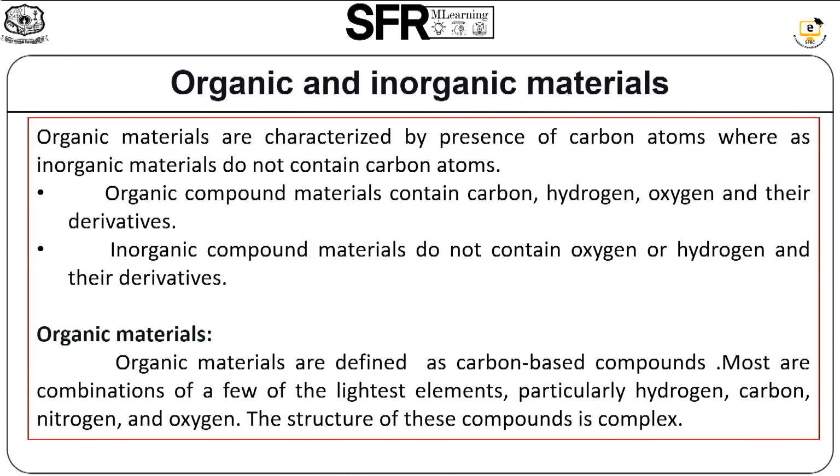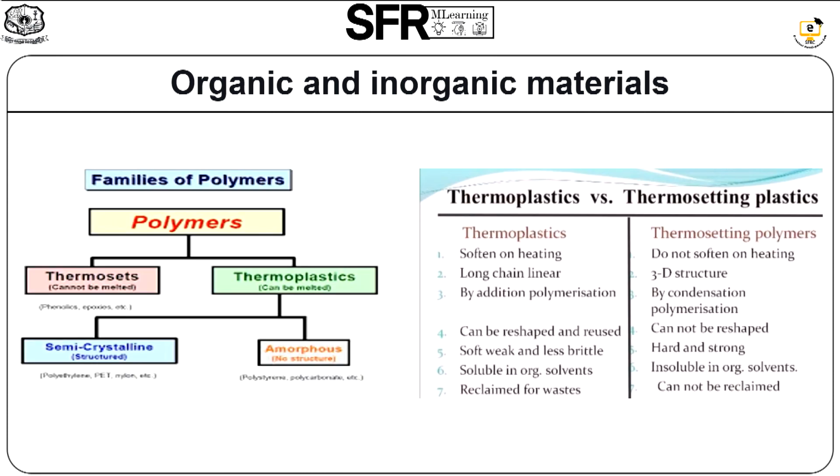The organic polymers are prepared by polymerization reactions in which simple molecules are chemically combined into long chain molecules or three-dimensional structures. The organic polymers are solids composed of long molecular chains. These materials have low specific gravity and good strength. The two important classes of organic polymers are thermoplastic and thermosetting plastic.